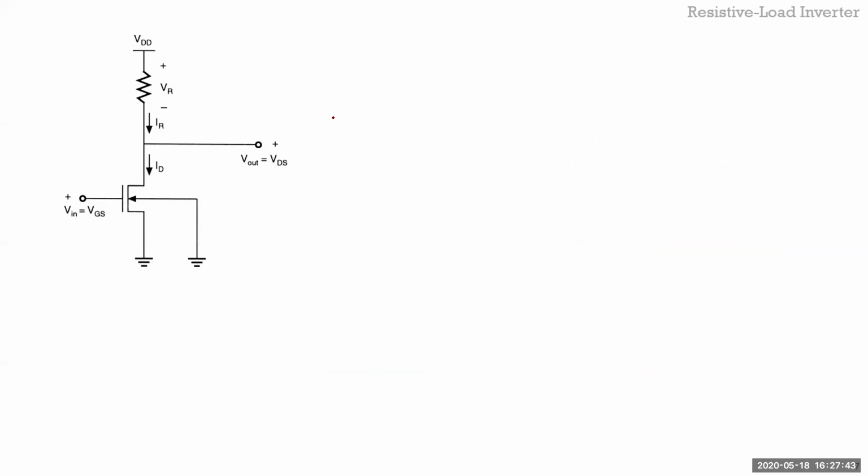Okay, so now that we have the definition, we'll take a few gates and do some analysis. When you're doing static inverter characteristics, essentially we are just doing noise margin and power calculation, most of the time static power calculation, not the dynamic power. The power involved in charging and discharging the cap, you don't do that with static analysis. You just do what's called static power, and I'll explain it a little bit after. I won't go much deeper into it.